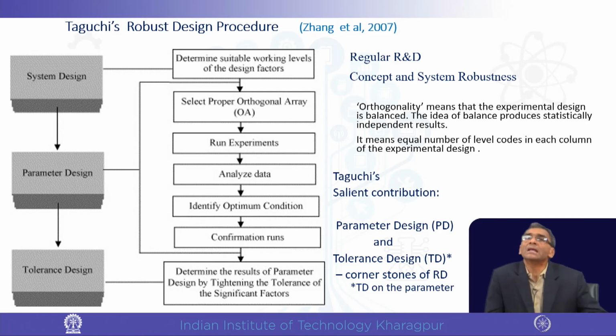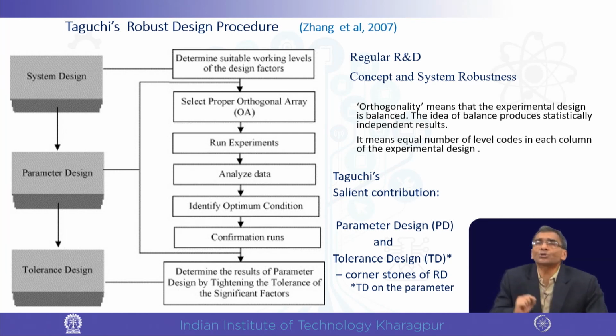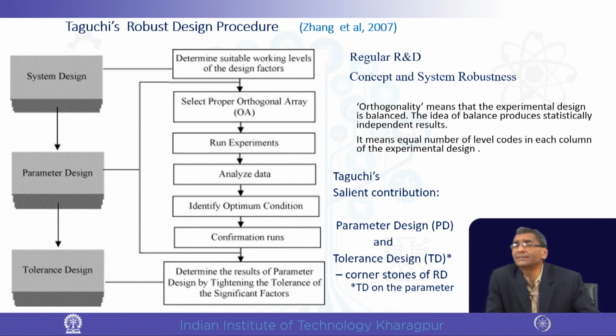What is tolerance design? In short, when we are deciding a parameter to be of a certain scale and set, we are saying that this parameter should also not fluctuate too much. If we see that a parameter is 60, to what extent does that give the best result, whether it is 60 plus or minus 1 or plus or minus 2, etc. So within which range we have to come down so that the performance is intact. How tight the tolerances are to be made is the direction given by the tolerance design.